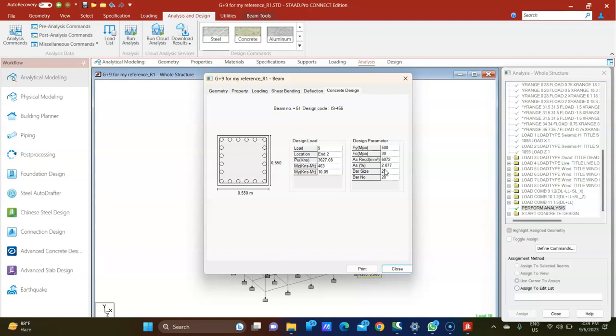Sometimes we have seen in some hotels that in the lower 10 stories the reinforcement is 1.5%, and above 15 stories the reinforcement is 2 something percent. Generally, a higher percentage of reinforcement occurs at the bottom floor level, but here it is reversed. If it happens, it will be due to the lateral force, the earthquake force, right? Any question?